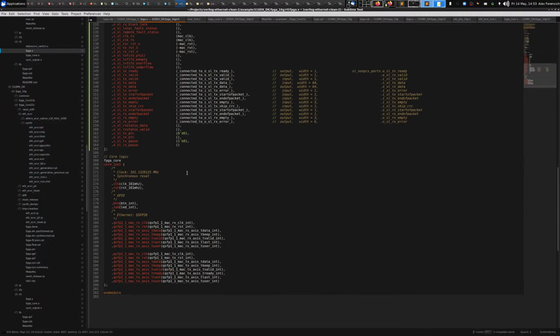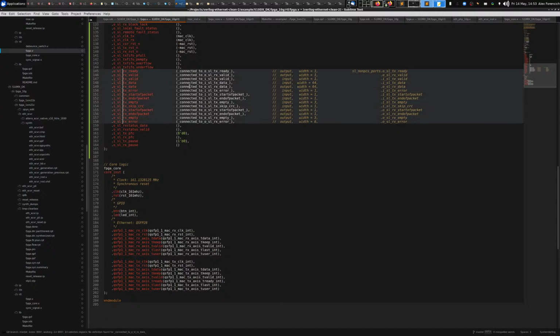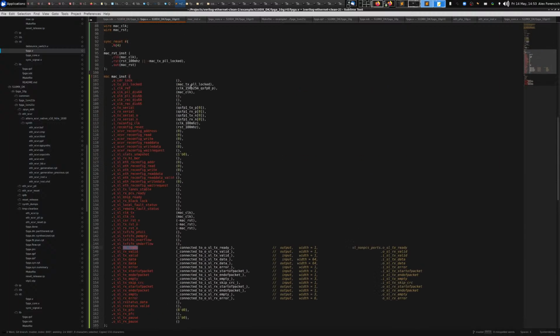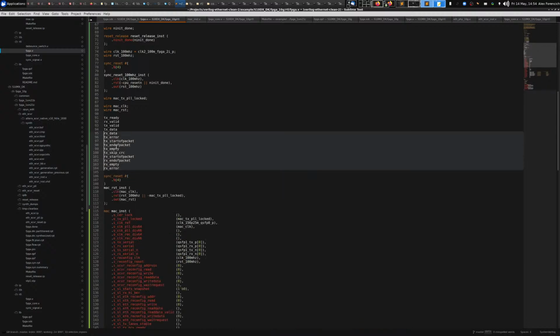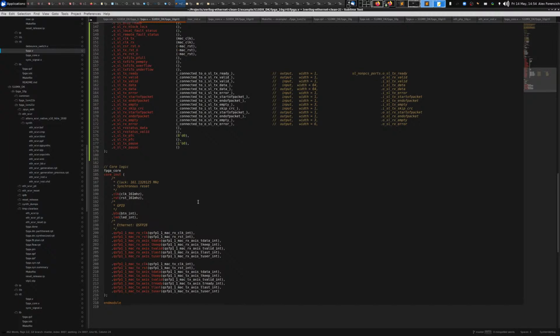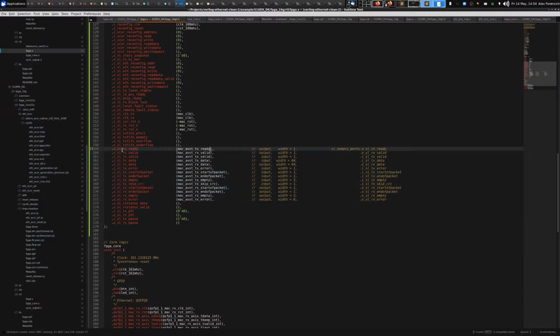Okay, all right, so the last thing I need to do now is adapt between Avalon and AXI. So go ahead and take a look at this. I have all of these guys here, right? Okay, so I'm going to go ahead and create some signals for these, for all the streaming connections. All right, so I'm going to go ahead and make that Mac AVST.